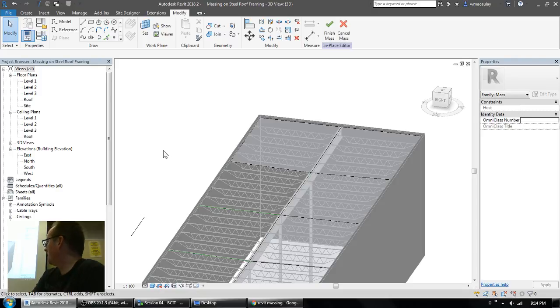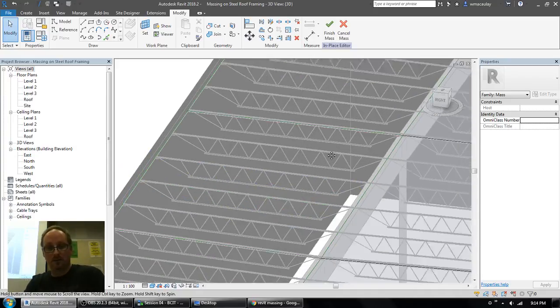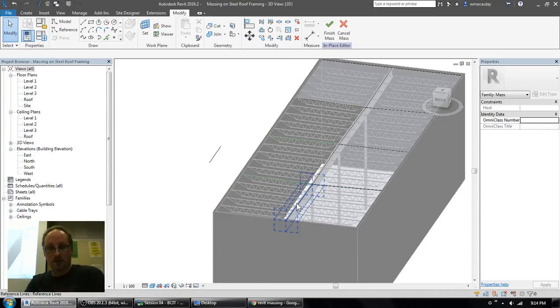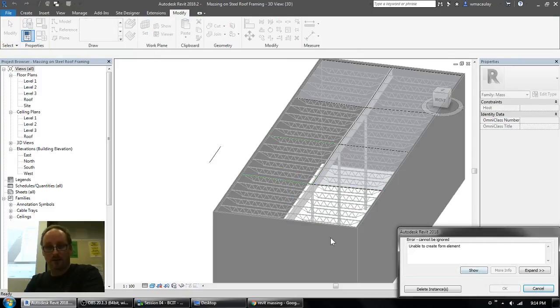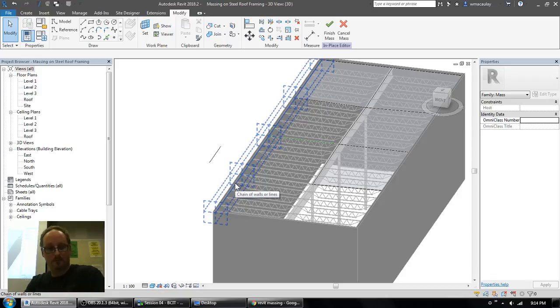So I'm making surfaces anytime where I've got a break in the structure, and I'm going to skin a roof onto these massing surfaces. So again, just so you can see how I created it from scratch, I'm going to delete these reference lines down at the corner here. So I'm going to delete that one, and it's deleting that mass there, of course, because those are based on reference lines.